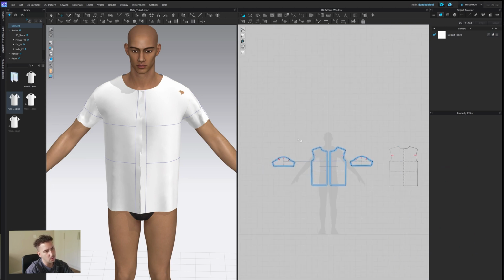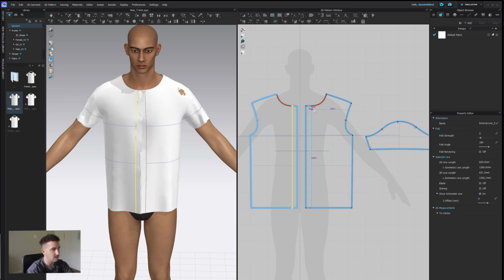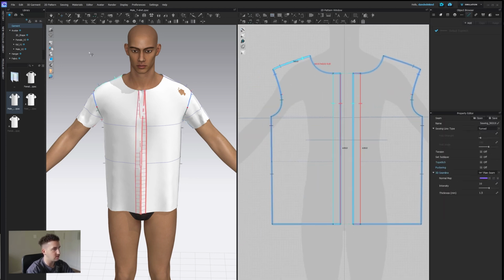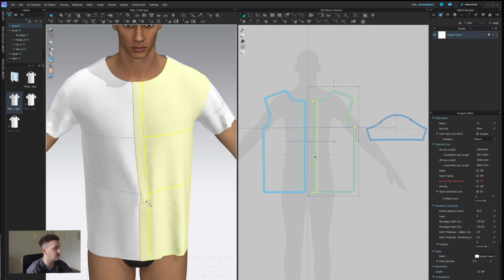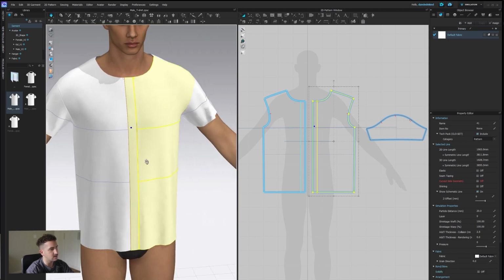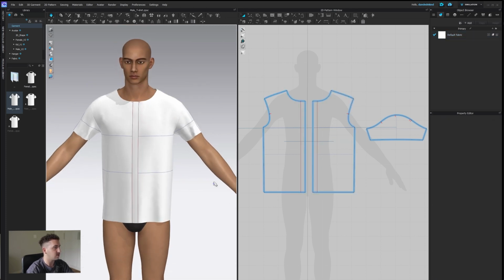And also, if you're wondering why this is transparent, it's because I have transparent surface enabled. Normally you just have front texture surface. We're then going to create these internal lines. So let's just use our internal polygon tool and bring this down. And you'll see it will be set to both because it's symmetric. And then we can just sew these two together. And then we're going to set sublayer for now so that everything's just attached. You'll notice that the one side isn't loose, but we'll adjust that at the end. We just don't want to remove linked editing now, or else it will be hard to adjust both sides equally.